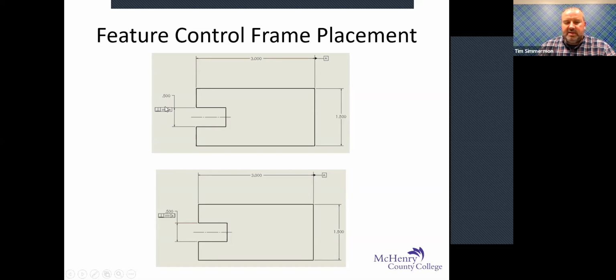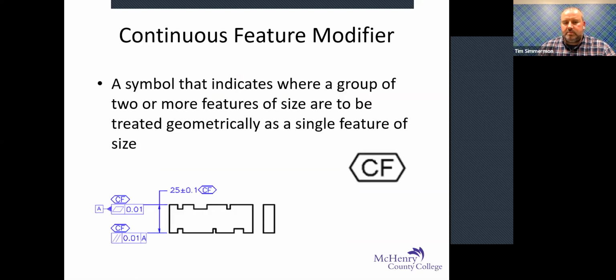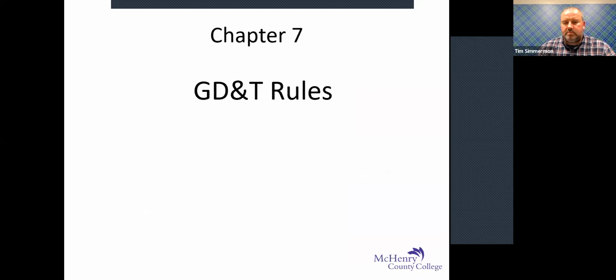And 10 thousandths, that's the machinist way of calling that out. So if the weatherman would call that, I always forget what they would call it, 10 hundredths or something like that. But perpendicular within 0.010 inches to datum A.